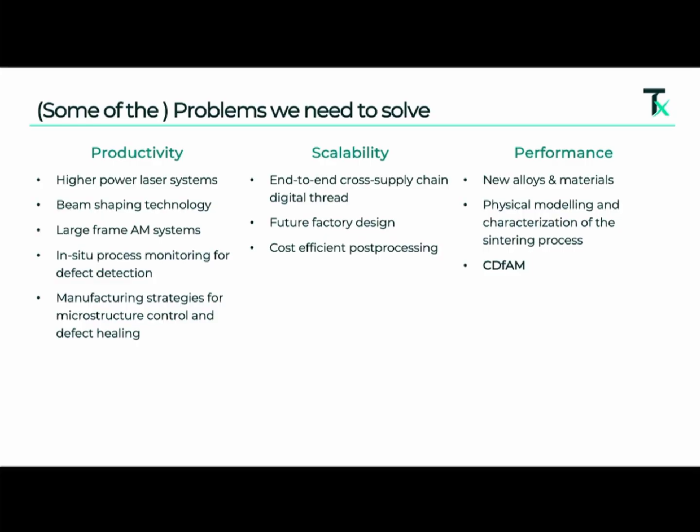So at the moment, even the biggest metal additive machines in L-PBF, and I guess other manufacturing processes as well, are pretty space constrained. Maybe the biggest ones are about half a meter by half a meter by half a meter, right? So anything bigger than that, you can't make it. That's a problem. Laser power, parameter choice, beam shaping, choosing the size of the laser, and so on. Anyway, loads of stuff here, lots of words. This is a boring slide.